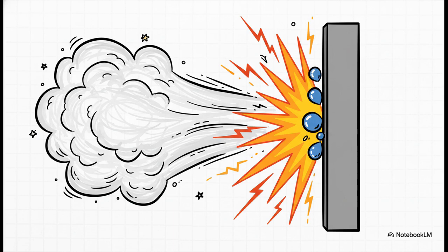When steam hits a surface and condenses back down into a liquid, it violently dumps all of that absorbed, hidden latent energy directly onto that surface as sensible heat. That is what gives you continuous heating at a constant temperature. It's exactly why steam is the ultimate heavy industry heating medium, but also why a steam burn is so uniquely devastating compared to a hot water burn. You are literally getting blasted with hidden energy.